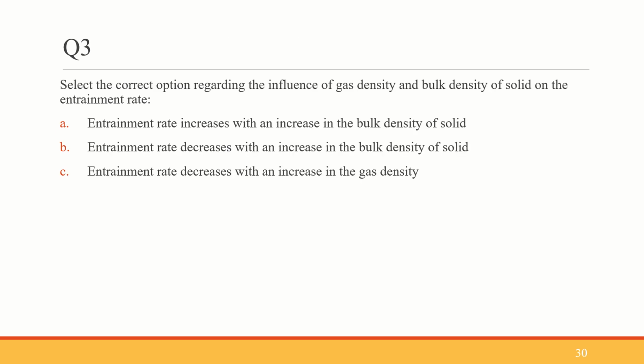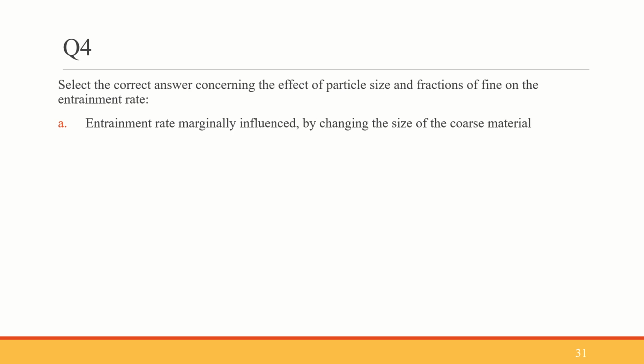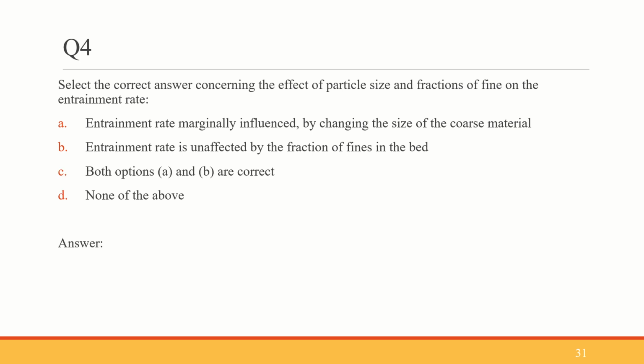Entrainment decreases with increase in gas density, and it decreases with increase in bulk density. So options C, B and B are right. And later, entrainment is marginally influenced by changing the size of the coarse material. It is unaffected by the fraction of fines. Both are true statements.